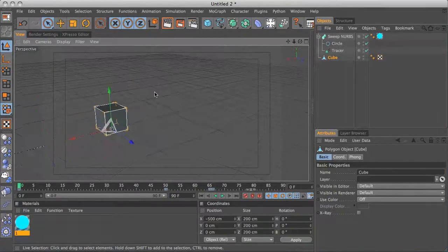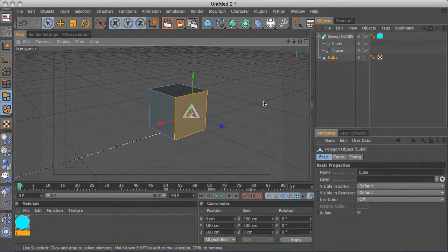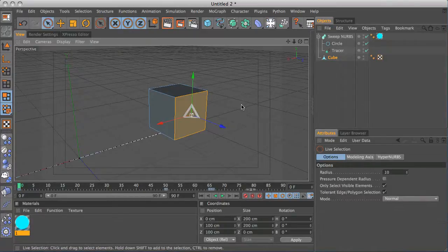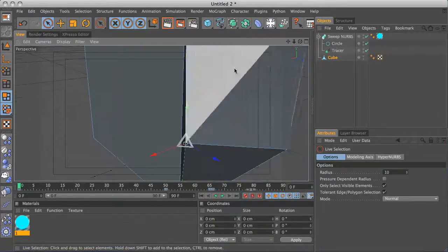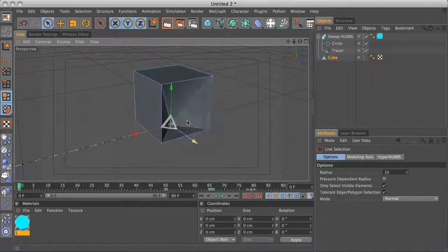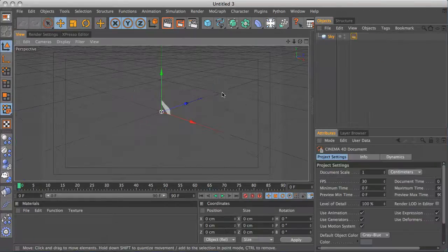I'm going to flip around here and go over to this face and hit D for an extrusion, and I've got a 0 offset. So I've got that extrusion there, which is fine, that's what I want. Now I can take this back. Now you can see it might have added a point that we don't want. It's in fact taken it to the origin, and that's because we've keyframed. But what you could do is do a 0 level extrusion. Let me show you what I mean.